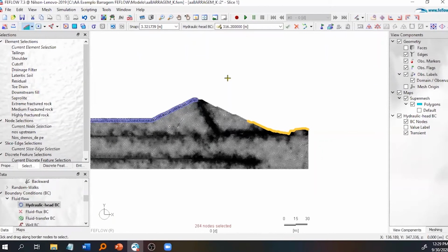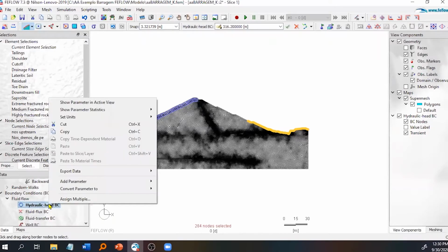If there is water that comes into the system, then the head disappears, or there is no boundary condition. Basically showing that if the head wants to go higher, it keeps there. But if the head wants to go lower, it can. It's similar to entering a hydraulic head, but adding a constraint where you say there is only a certain, now min and max depend on the direction, if it's leaving or entering the system.